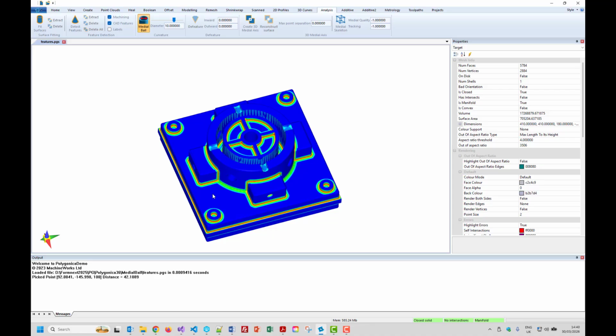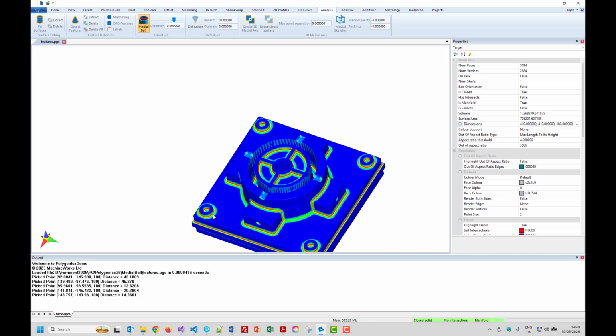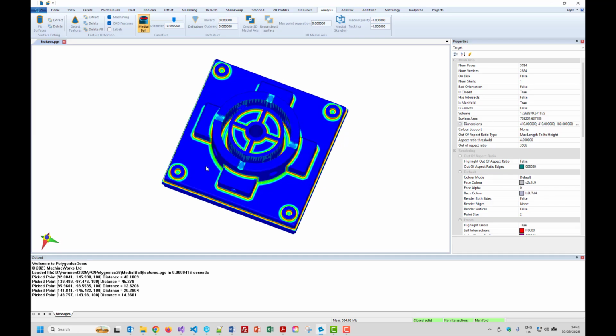Okay, and if I click some points on the surface, for example, here, it's telling us 42, so you could fit a 42 millimeter ball there, and similarly here you could fit a 45 millimeter ball. If I go nearer that wall, I can fit a 12 millimeter ball. Nearer this island, I can fit a 20 millimeter ball here. That's partly because the island's lower, so here you've got a large wall, whereas here you've got a low island, so the sphere would go up kind of like that.